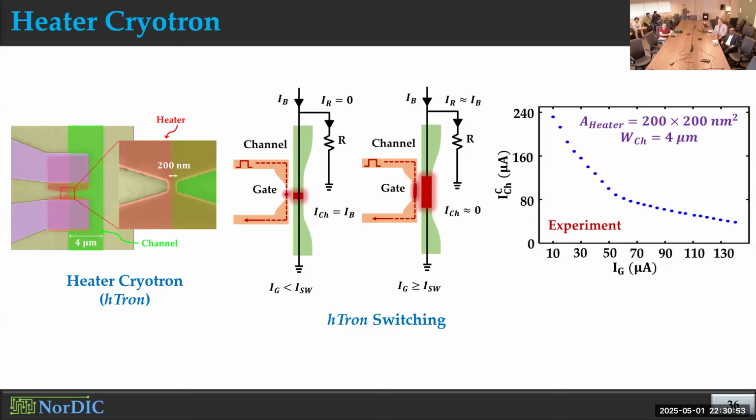The material that they used here was tungsten silicide as the superconducting material, but there are experimental data for the same device with niobium nitride, niobium, and all those other superconductors as well. In some cases, we have different current levels, different resistance levels. Their speeds also vary, like the switching speed also varies. So yes, we can have different options.